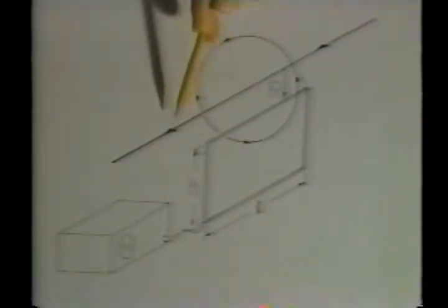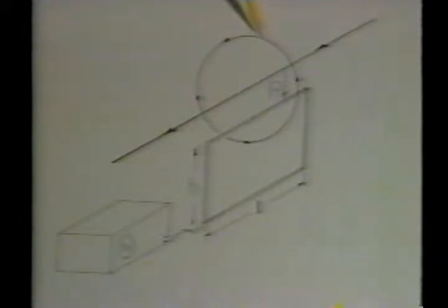The current and hence the field are varying at 60 Hertz, so this integral has a time rate of change. Applied to the coil, the line integral on the left becomes the negative of the terminal electromotive force or voltage. Here is the induced voltage in the coil. The total flux linked by the coil is lambda sub F.